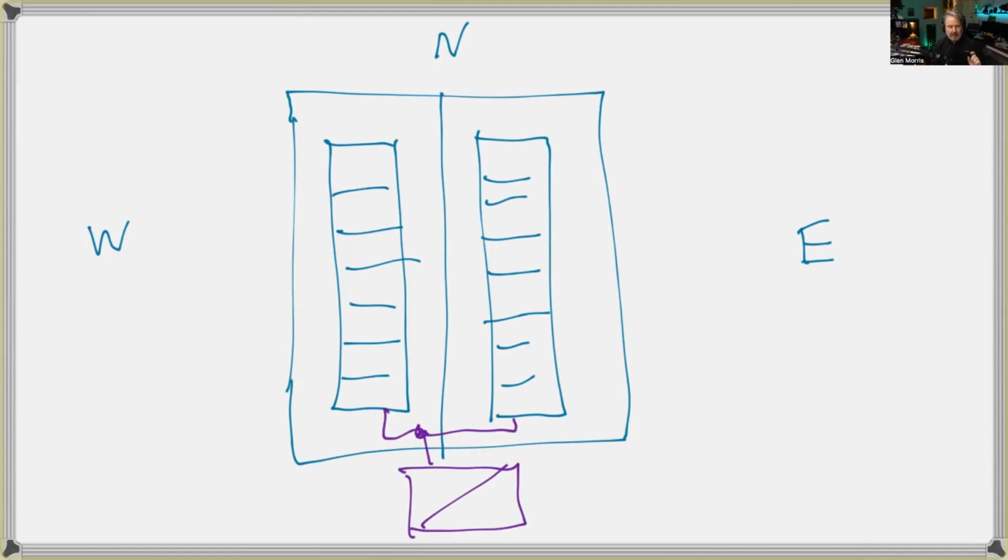But, and there's a big but, you can only do this if the number of panels is the same. Let's say we've got 8 panels here and 8 panels here. They have to be the same because the string voltages have to be the same. So you can do it. The other question is, is it a good idea?